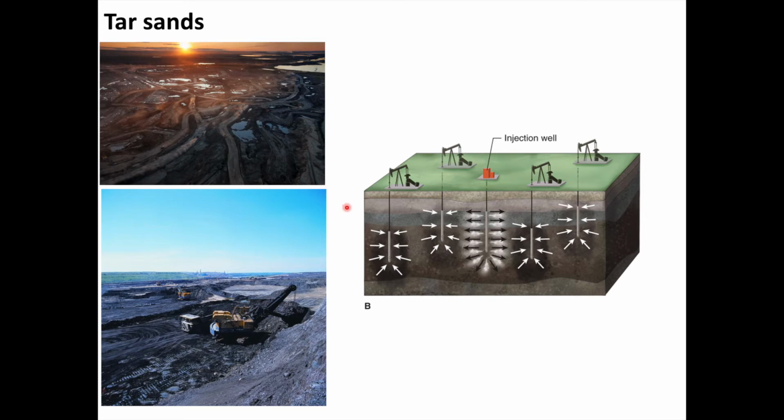Another 40% of tar sands oil is from steam injection, in which steam is injected into a well, lowering the oil's viscosity in the surrounding deposits. The thinner oil is then pumped until resistance again becomes too great, at which point the process is repeated. Another method shown on this slide involves a dedicated injection well surrounded by 4 pumping wells.